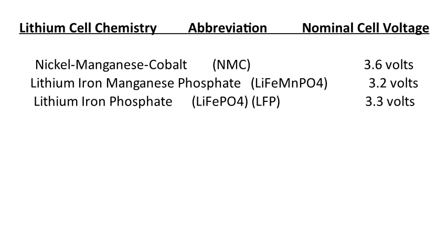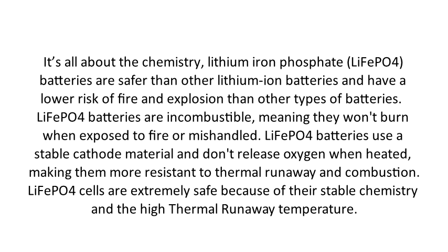When it comes to lithium cells, there are a lot of different chemical combinations. So for the sake of keeping things from getting too confusing, we'll refer to lithium iron phosphate, LiFePO4 or LFP cells, unless otherwise noted. The reason for this is they offer the greatest number of life cycles and are by far the safest battery chemistry available at this time. It's also the chemistry with a voltage that best matches most of the devices we'll be powering.